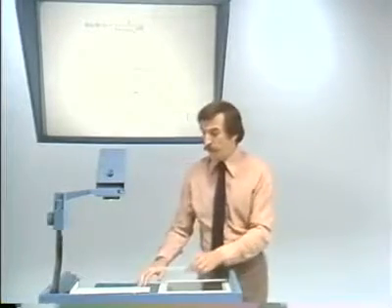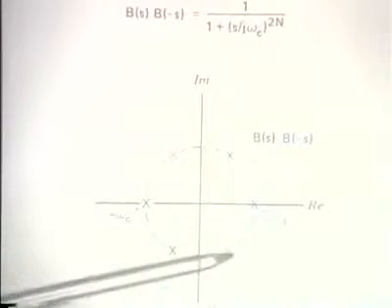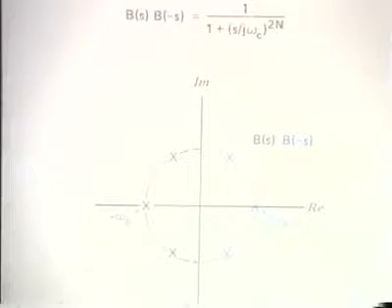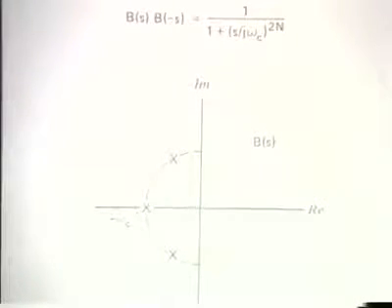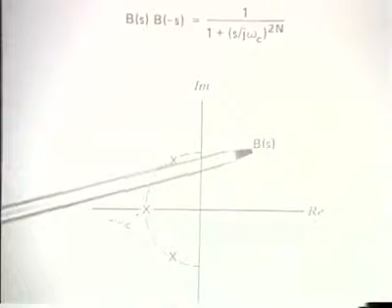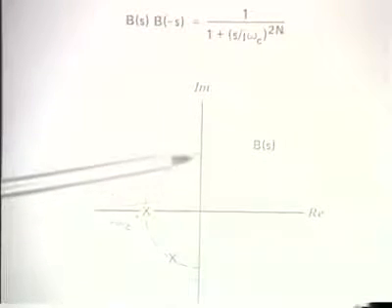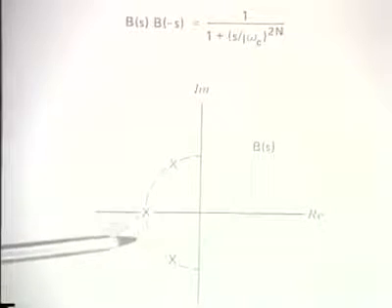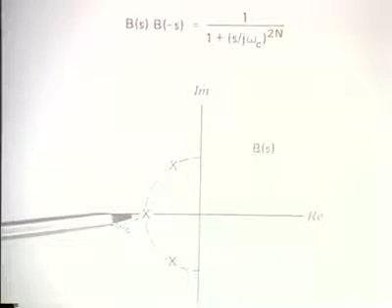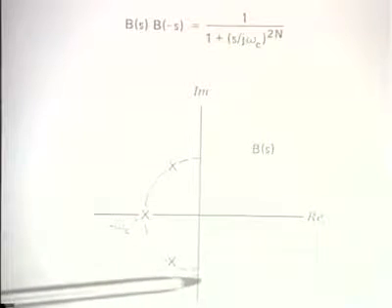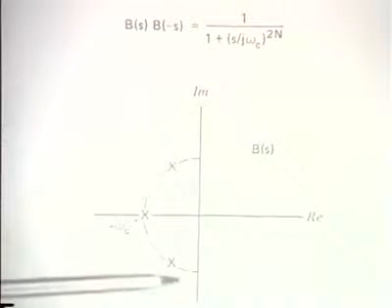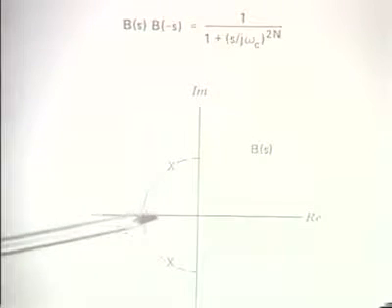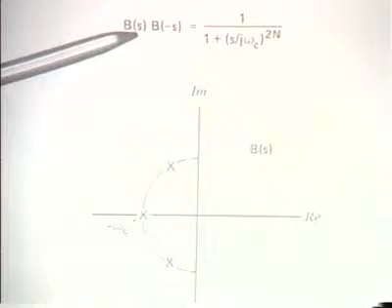So in fact, out of each of these pairs, we would associate the left half plane pole with B of S. And so the transfer function for the Butterworth filter, for this particular case where this designates the parameter omega sub c and capital N is 3, namely a third order Butterworth filter, is this set of pole locations. Given those, of course, we can figure out simply through algebraic means what the transfer function B of S is.